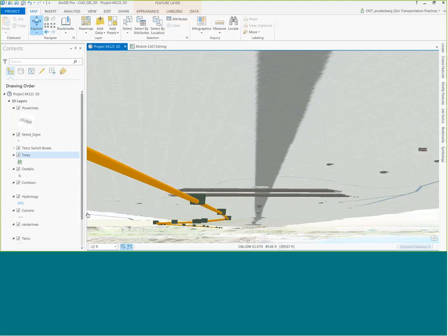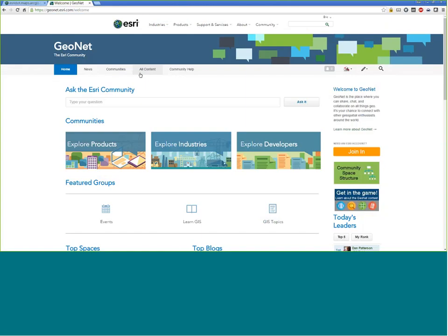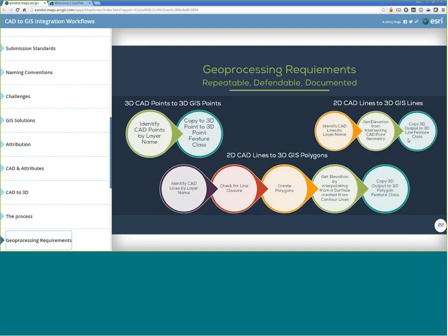So I'm using those elevations from those nodes to populate the ends of those lines, and once we have those elevations, we've got 3D lines, and we can represent those lines with the appropriate pitch. And then if I know things like the diameter of the culverts, then we can do some really crazy stuff. We can model out the culverts to their appropriate size as they would appear if you were inspecting one. So there's lots of possibilities here once you start populating that data.